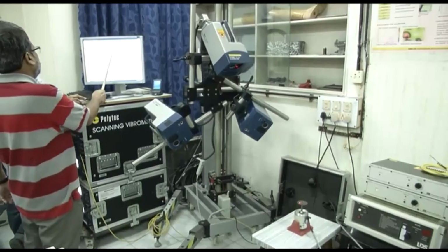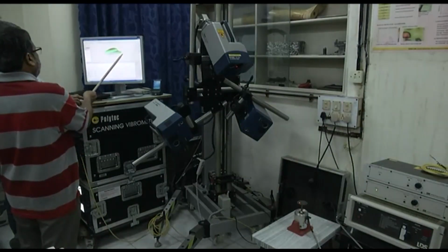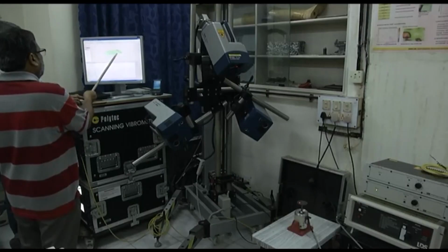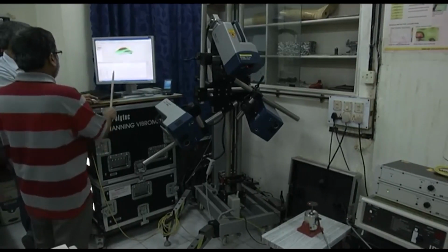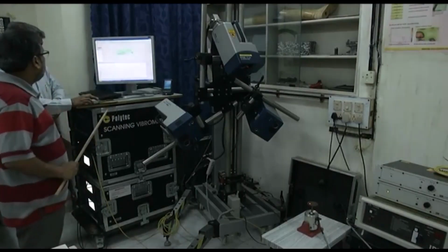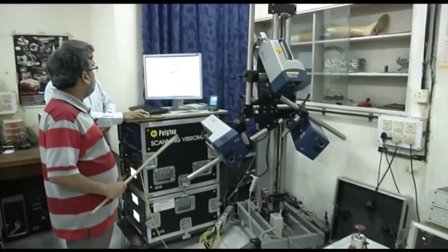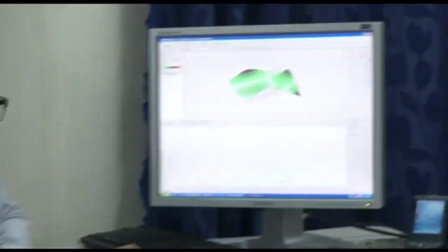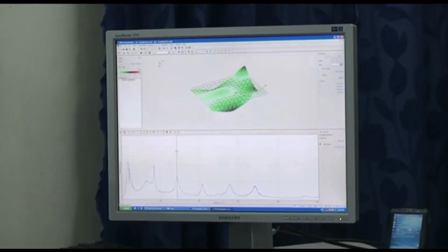Like in this particular case, it is vibrating in a way that it is the sides of the plate, so it is one of the width modes of vibration that we are finding here. Can we come to this mode, for example? Now you can see that it is a kind of torsion and bending combination that is happening to the system. So like that I can actually get each one of these modes.